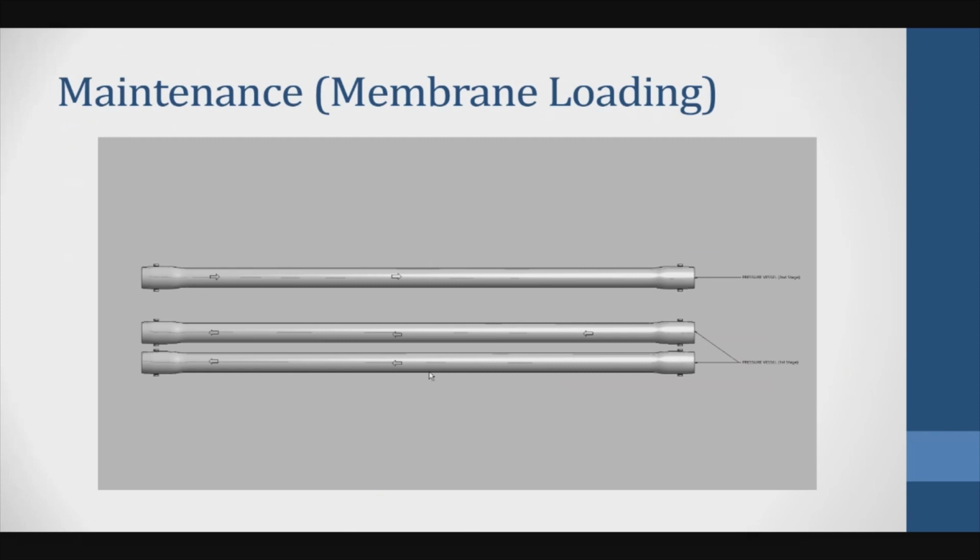As an example, this system has a 2-1 array. That means those two pressure vessels represent the first stage, and that second one represents the second stage. So the water is going to come from here, go equally into those two pressure vessels, and travel like this. Inside those pressure vessels, I would guess about 5 membranes each. Then the reject water from both pressure vessels will feed the second stage. That means the water produced from those two pressure vessels would have a better quality than the second stage. The reason we have 2 stages is so we can save water and achieve higher recovery.